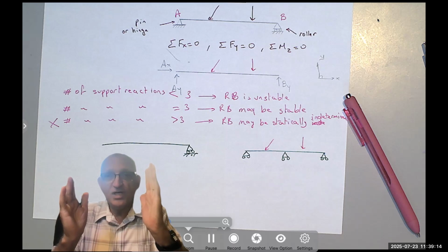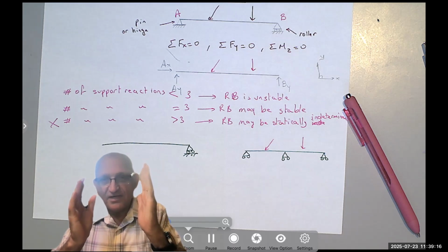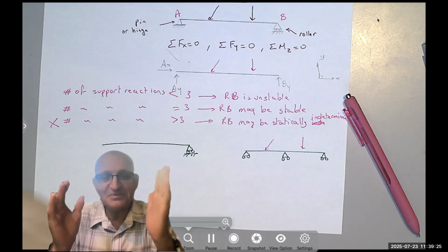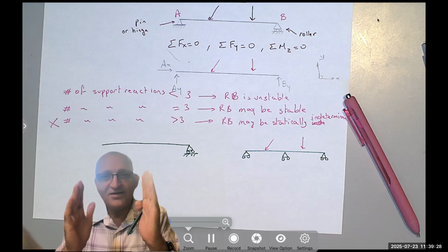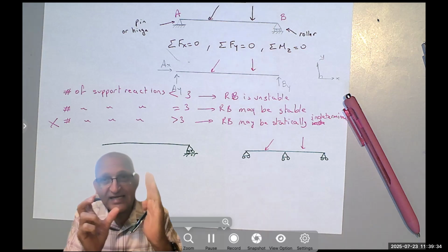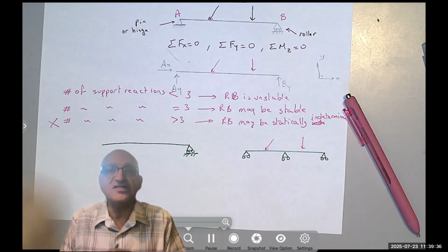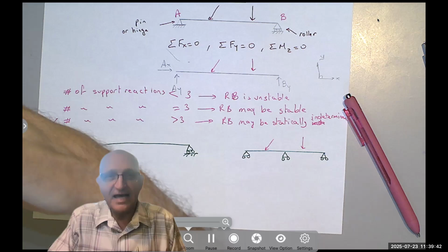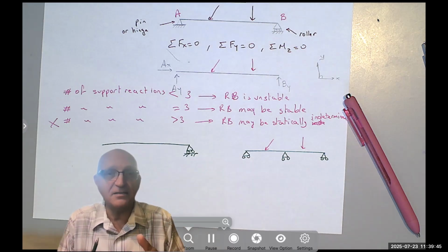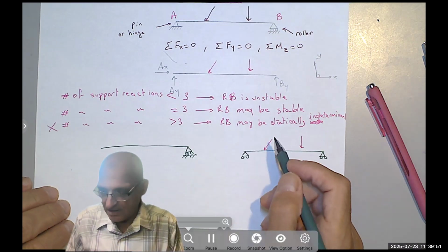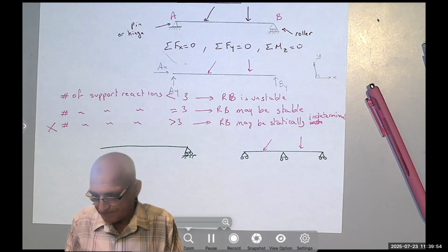If you are trying to keep the length of a beam without expanding and you heat it up, you can feel that it's pressing on your hands, not your hands, of course, I'm just talking theoretically, okay? Because you are preventing it from expanding, that prevention produces internal stresses. It's as if you are compressing the beam and having some stresses and deformation inside the beam. So that's why we cannot, using statics alone, find these forces.